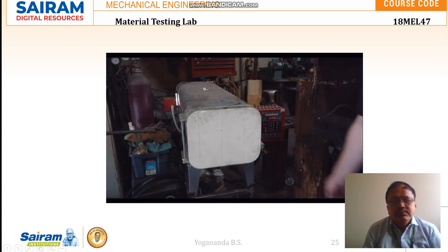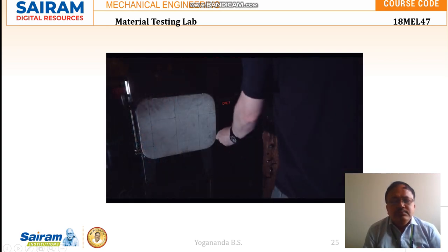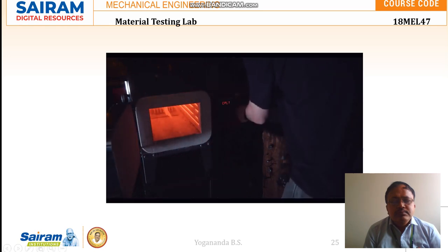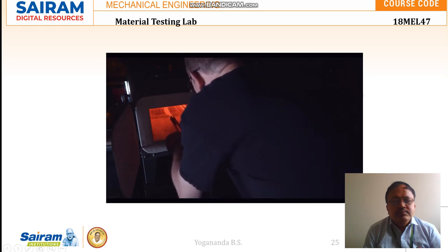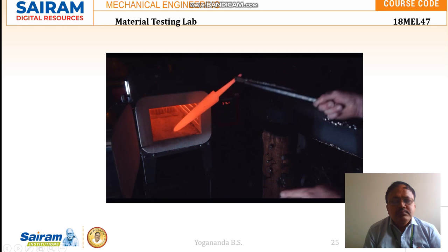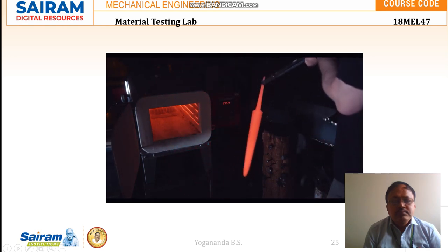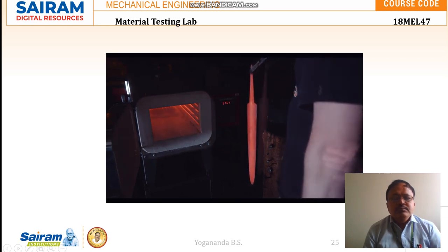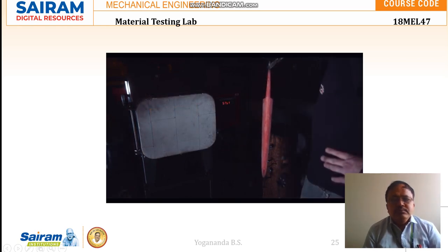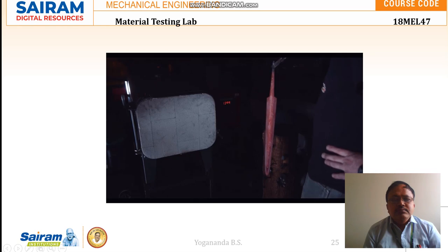Since steel is in crystal form, the repeated heating in the forge causes the steel to form larger and larger grains that make it brittle. Slowly cooling it down from its critical temperature reduces the size of these grains. This is also a good opportunity to check for warping, which may occur when the bevels have been ground unevenly. I was also hoping to show you some recalescence, which happens right when the carbon in the iron matrix transitions from austenite to ferrite. That transition releases visible heat. You have to check my spear video, where you can see that clearly. Here, I unfortunately stepped into the video.